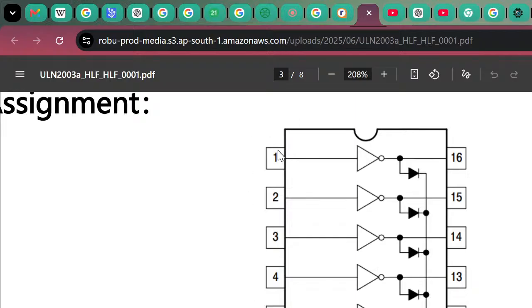If you toggle the state of these 7 GPIO pins between high and low, the relays will function accordingly. That relay can control high voltage, something like a bulb connected to 220 volts, which can be turned on and off. Simply by toggling the state of the GPIO pins of the microcontroller from high to low or low to high, you can control a high voltage application.